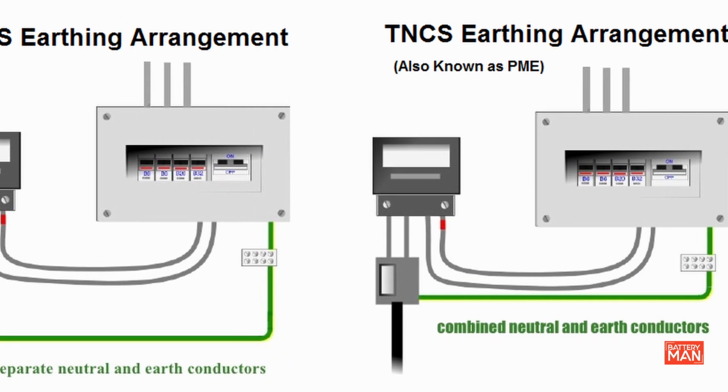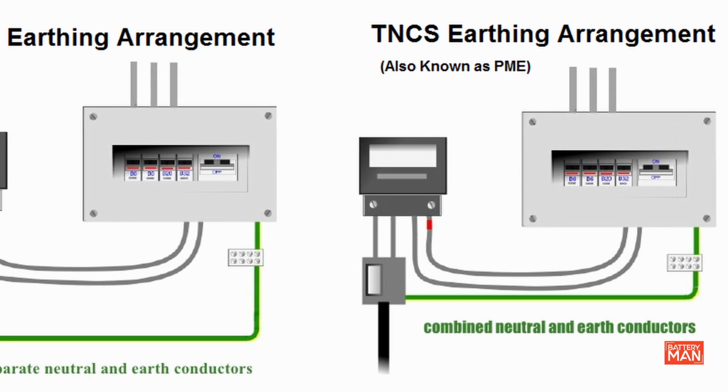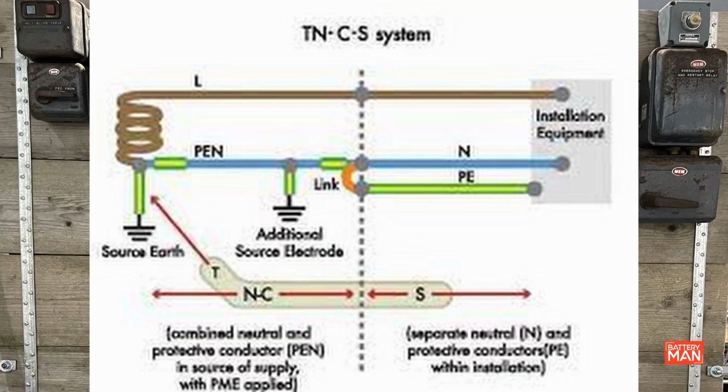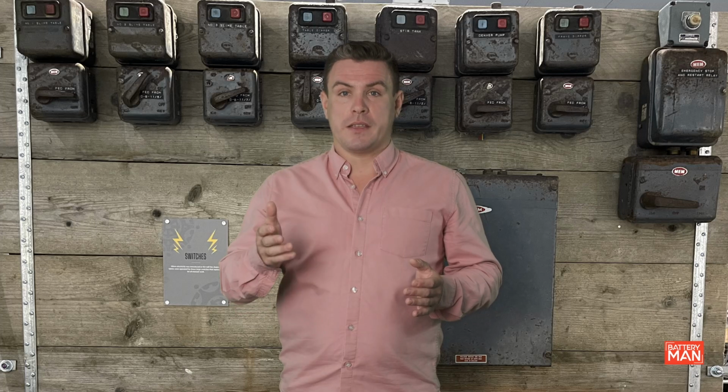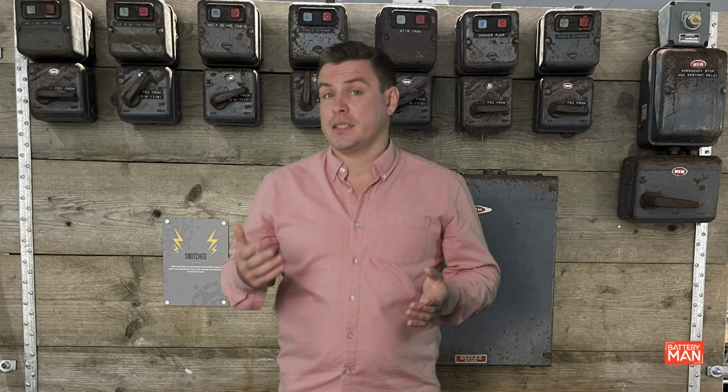We work out the Ze by disconnecting the earth from the earthing block and testing between the earth and the incoming line. Notice that this is carried out on a live terminal, but with a dead board. Okay, so we have the Ze using our testing device.